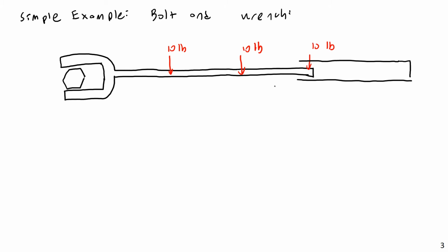If you put some ridiculously long moment arm onto the end of a wrench and try to turn the bolt that way, you may apply so much moment that, looking at it in profile, the bolt is going to look something like this. The threads are there, with the head of the bolt here.